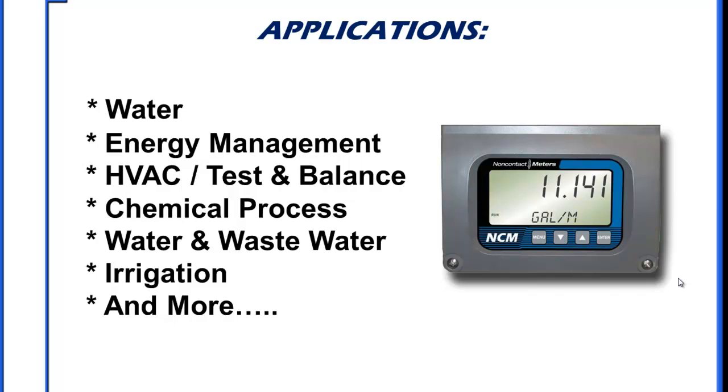Well, in any aqueous base application, quite frankly. It works in ultra pure liquids up to about 2% suspended solids. Applications with a higher level of solids traditionally are used by what's called an ultrasonic Doppler flow meter. And a Doppler flow meter basically needs chunks of stuff in the process liquid to do a good job, and they don't work on clean liquids.